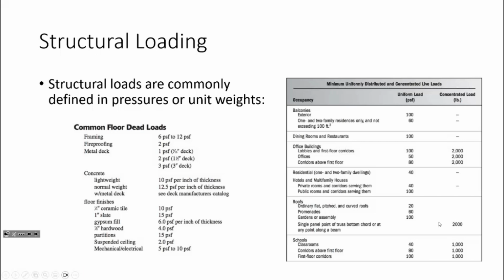Well, if you're a structural engineer working with the developer, the developer doesn't want to have their hands tied: that has to be a hallway and that has to be a room. So usually when you're designing commercial spec office space, you design everything as if it's one big hallway, right? So you would use like 80 or something everywhere, okay? Now I am actually skipping some details because there's things like live load reduction and what have you, which I'm not really getting into. But I just want to say that's kind of the idea.